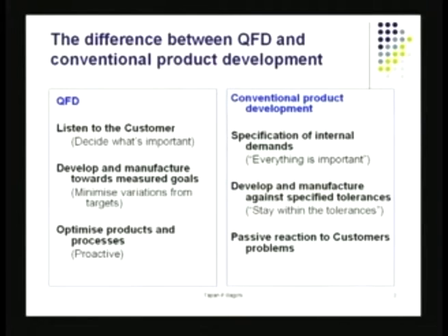Let's look at the conventional approach to designing a product. You start with what we call specification. So if it's a pen, what are the specifications of a pen? First of all, let's look at the two parts. We have the cap. The cap has a clip. If you look a little closer, the clip has a little tolerance there, so some numbers will have to be given. There's a length of that clip. Then you come to the top of it, there is a certain curvature that gives it perhaps some aesthetics. Then you look inside, there's a hole there, and the body has to go in there. And that fit has to be airtight so that the ink doesn't dry out when the cap is on.